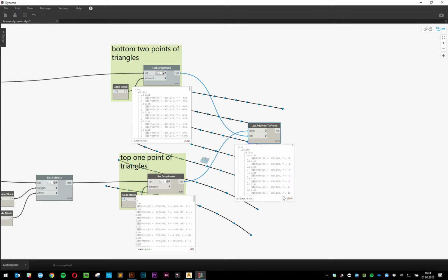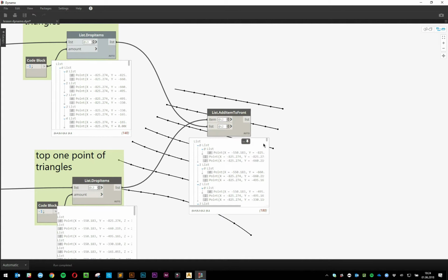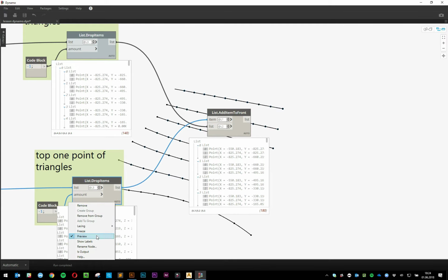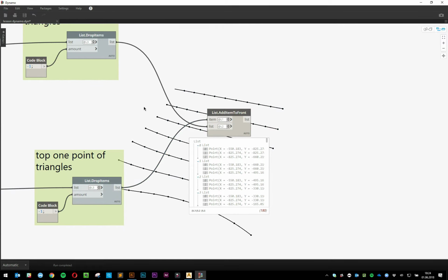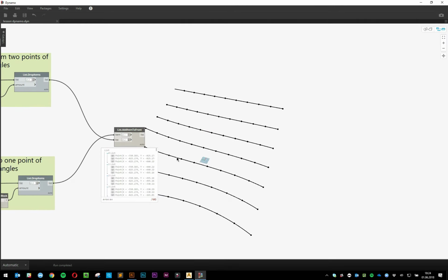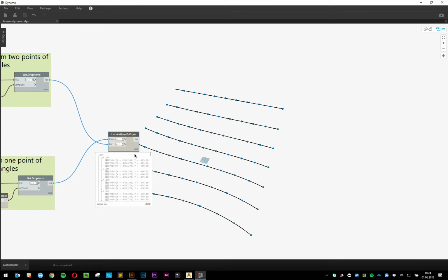And obviously there's a problem because we need to use list at level for both items. And usually what happens here is I just play with the levels until I get a sublist of 3 points flat, because here it's not. I could use the flattened list node, but let's just do it the proper way. Let's be clean. There we go, L1, L2, we get triplets of points. So let's turn this off. Close, close, save.